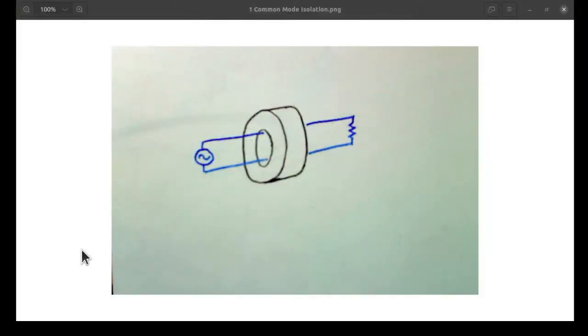Now I'm going to return to some familiar graphics here, and this represents the transmission line, be it twin lead or coax, matters little, as long as the entire circuit fits within the open space of this core. In other words, these two lines are continuous to this load. So they're hidden as they go through the core. This source sees this load and nothing else. The core,